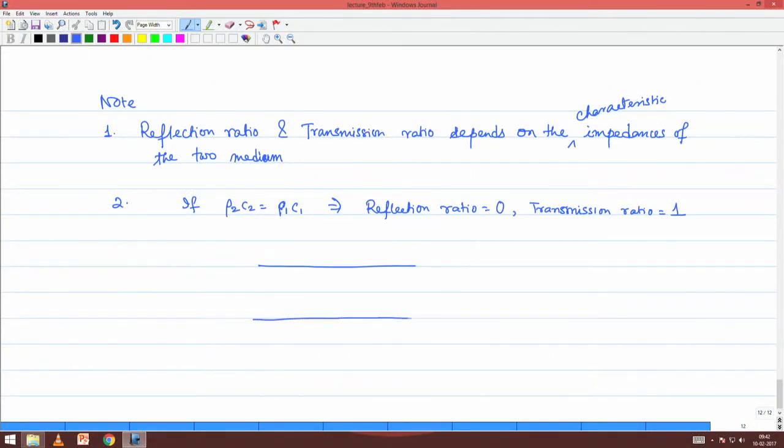So, I will just explain myself a little bit better. Let us say you have a plane wave which is travelling, let us concentrate within a small zone, and the associated impedance in this region is some rho c, right. Now, this domain is terminating in a wall, but this wall is made of a very special material, and the special material has the property that the impedance at exactly the same interface is at least approximately equal to rho c.